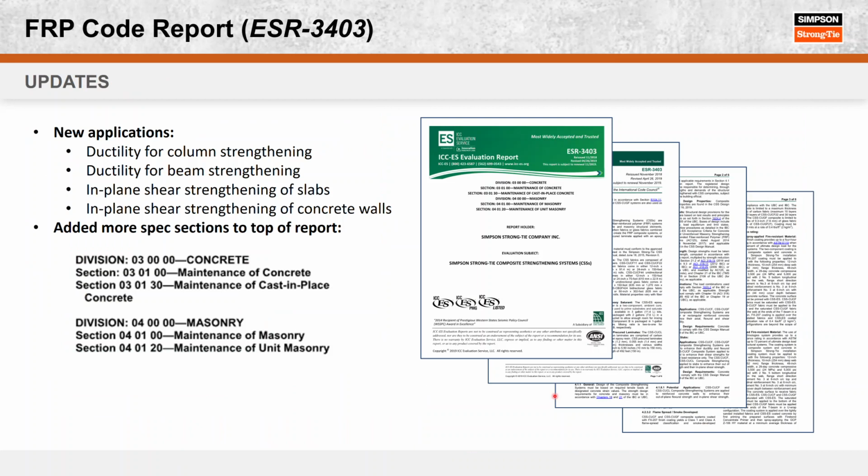And even if you haven't done a test on a certain kind of beam, you can still design that kind of beam. The code report is a little bit different, where they specifically say that you can only use FRP on a certain kind of member for a certain kind of loading. So the way design usually works is you take your materials, your concrete and your steel, and you can design it in any way you want to.